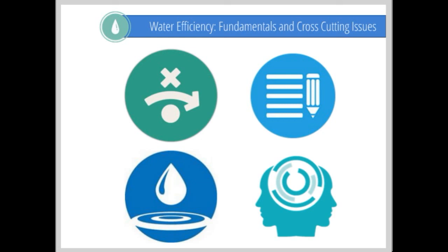Occupancy calculations. The Indoor Water Use Reduction Prerequisite and credit require projections based on occupancy usage. The Location and Transportation and Sustainable Sites categories also use project occupancy calculations. Review the occupancy section in Getting Started to understand how occupants are classified and counted.